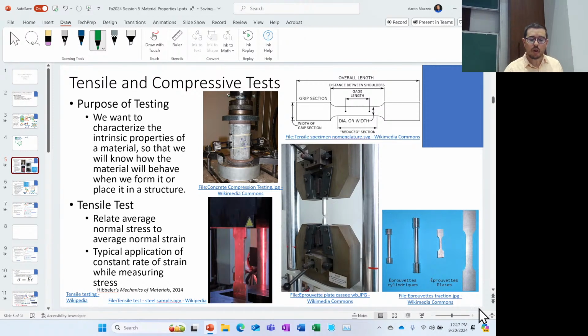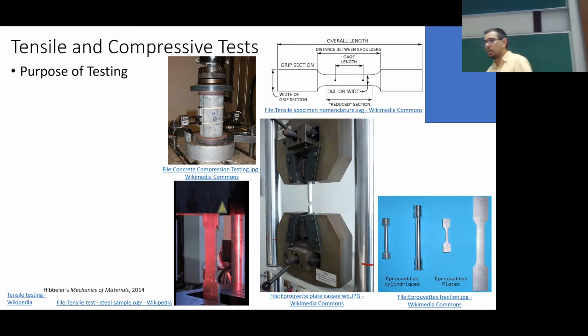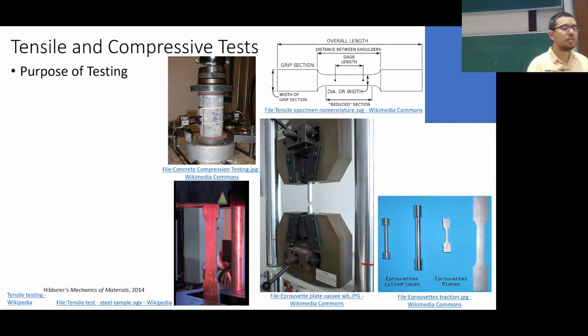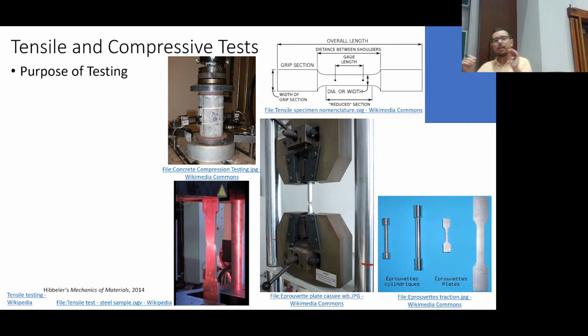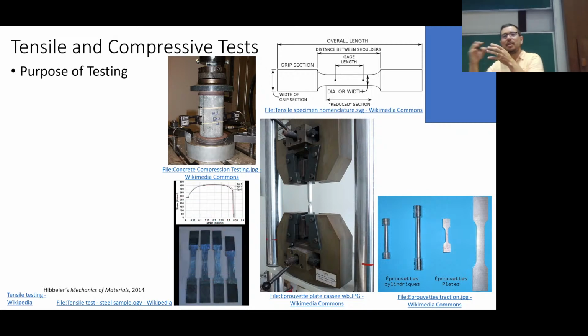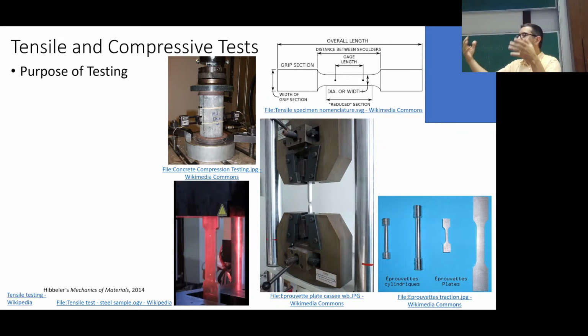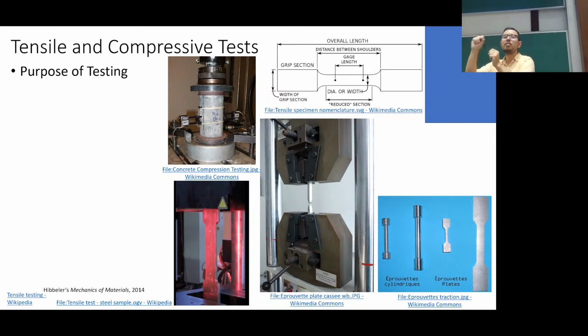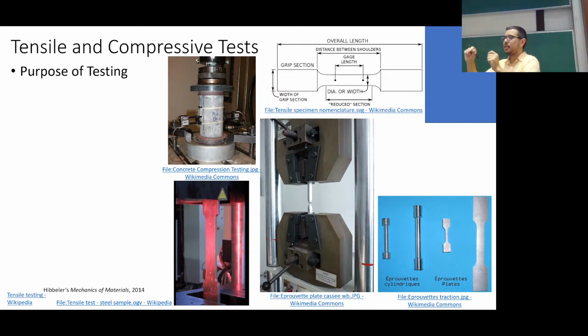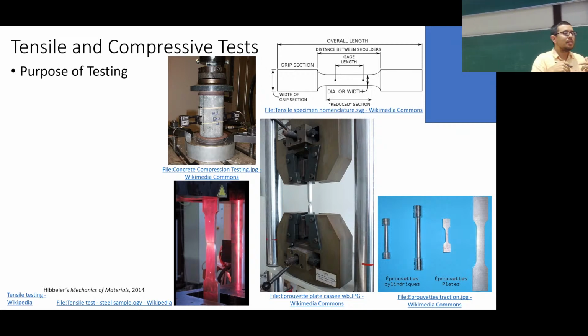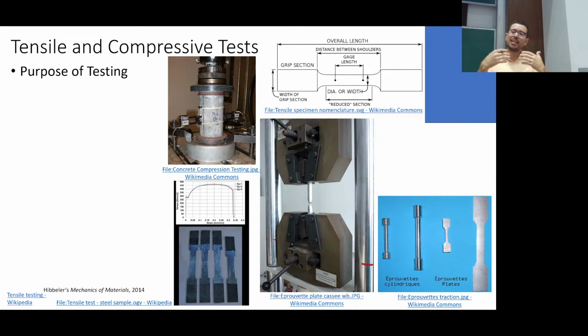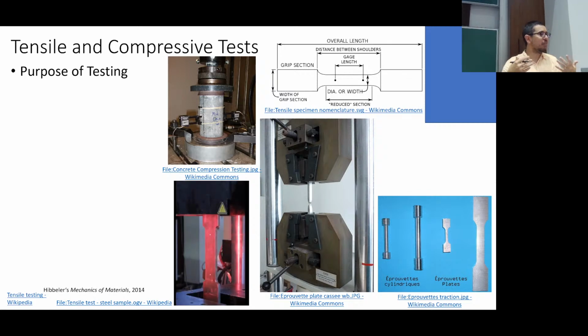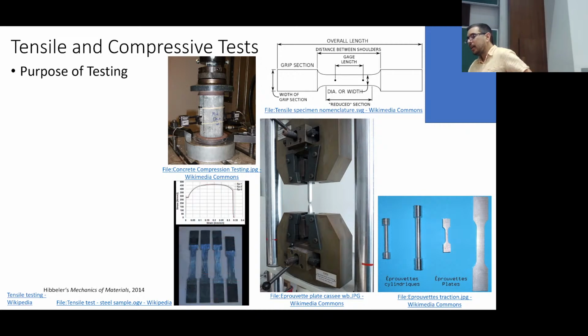Now, in order for us to relate stress and strain to each other, we have to know something about the material. So you're like, well, what are you talking about? You might not have made the connection. But we were calculating these stresses with the force, and then we were just saying, oh, here is some delta, and now calculate the strain. And we did do some connecting, right? We kind of connected through the idea that there's a stiffness, a K, for the structure. That's not a material property. That's a structural property.